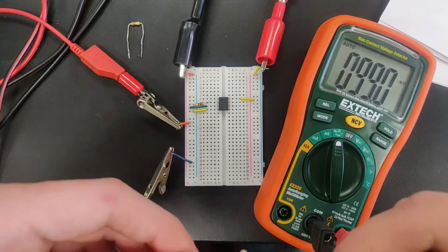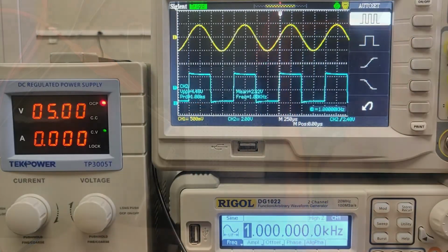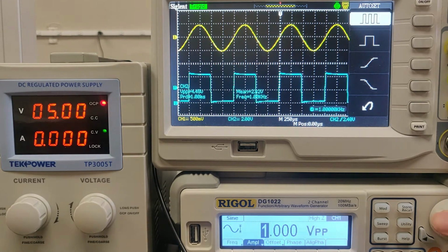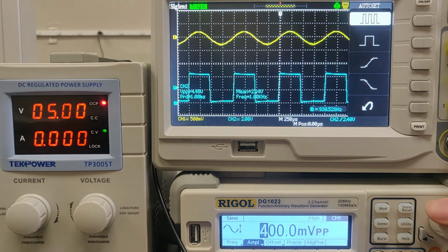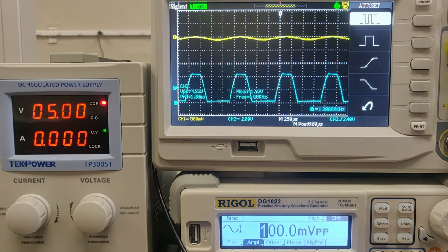All right, let's start the analysis. Okay, everything is hooked up now. So looking at the second step, we want to set our input voltage to 100 millivolts. So we'll decrease that. We want to set our frequency to 1000 hertz, which it is. And then we are asked to decrease the voltage and apply a positive DC offset such that we see our wave being displayed.